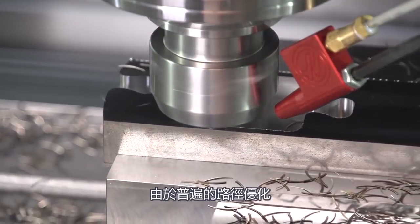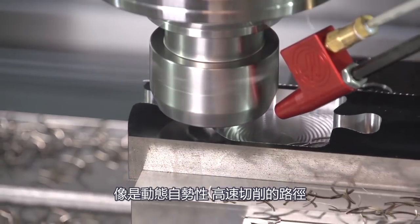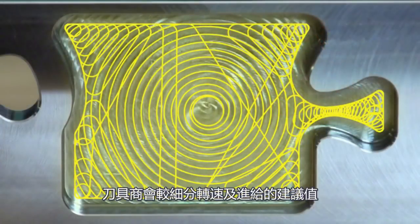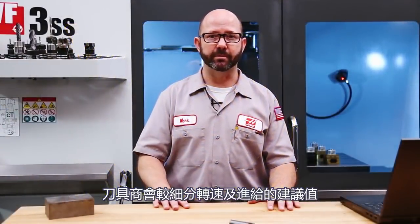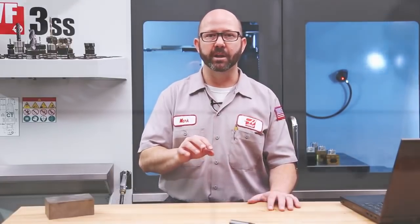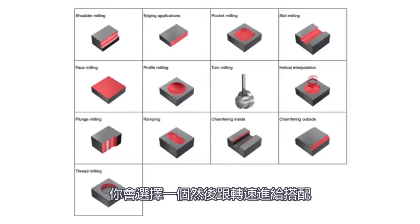With the popularity of optimized tool paths like dynamic, adaptive, volume mill type high-speed machining tool paths, the tool manufacturers are getting more and more specific with their speed and feed recommendations. So you'll often see charts like the one we'll show you here listing all kinds of different tool paths. You'll choose one and then match your speed and feed to the path that you're using.